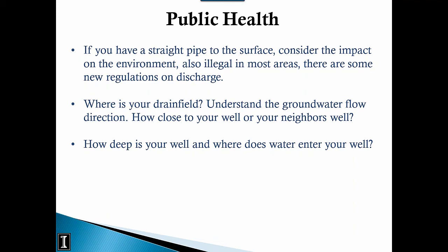Whereas a bedrock well, typically you construct a bedrock well, you seat the casing just 10 feet into the rock. So a 200-foot well could, it depends on how deep it actually is to bedrock. If bedrock's only 30 feet, you might only have 40 feet of casing. If bedrock's at 120 feet, then you might have 130 feet of casing, which is certainly better.